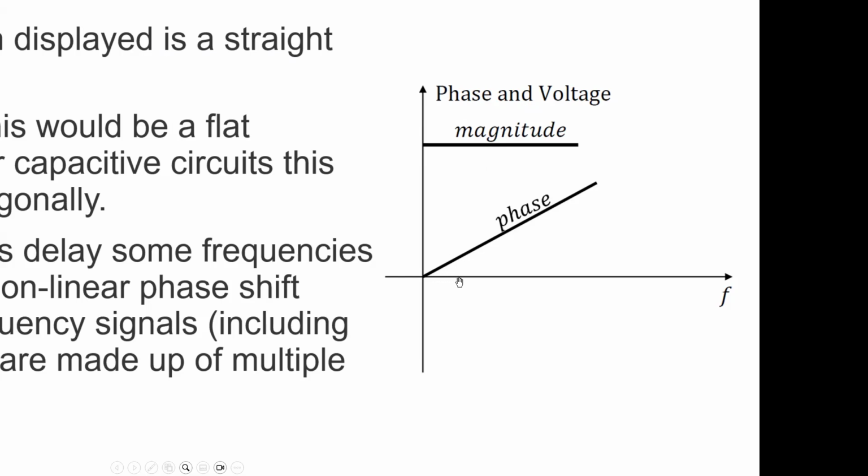So as the frequency increases with certain circuits, the waveform across different components can start separating in phase. They can have a phase shift. So let's say if the frequency increases, the phase shift between those two components changes, but it changes linearly. When the frequency goes higher, then the phase shift is that much. Frequency goes higher, then phase shift is that much. And if we get a straight line, then we're talking about linear phase shift between components.